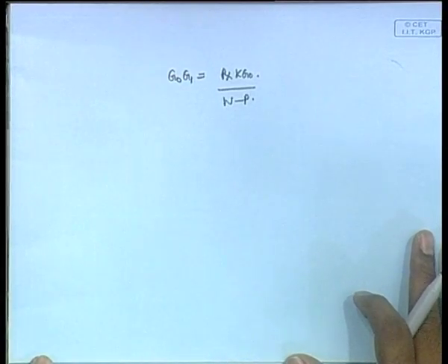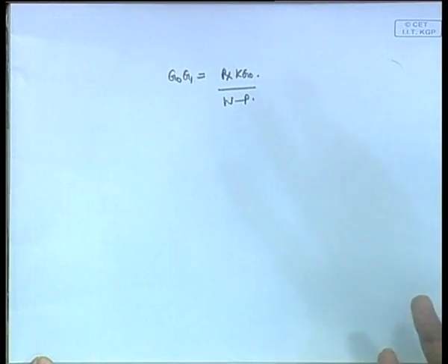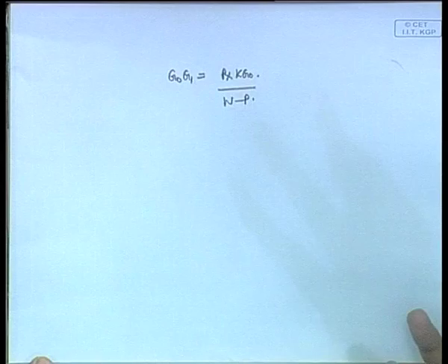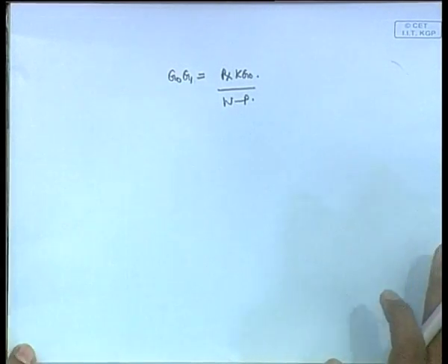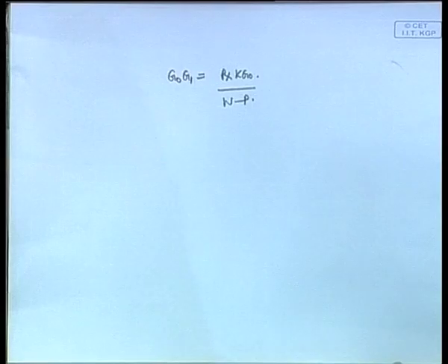Okay, this of course has to be given. kg0 has to be given; it's the center of gravity of the whole ship. kg0 means when the ship is designed, not about dry docking, when the ship is in its usual condition, what is its g0, that we need to have.